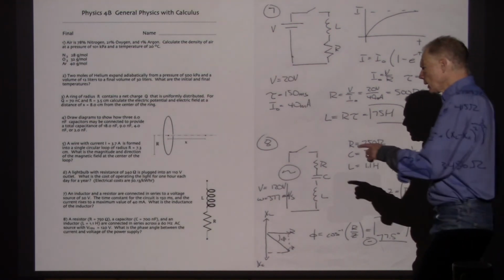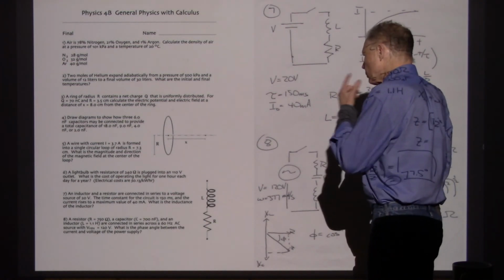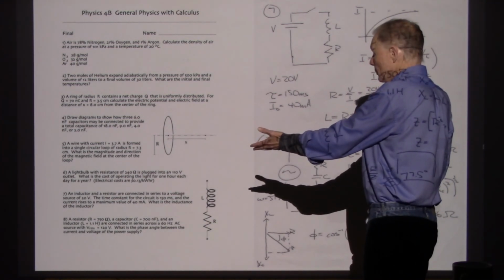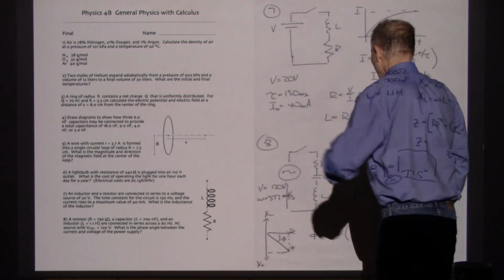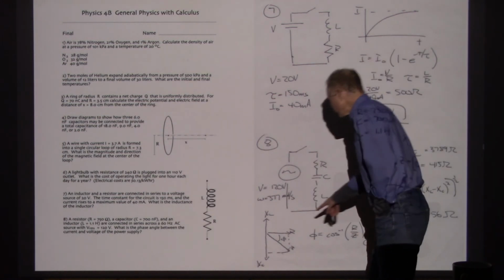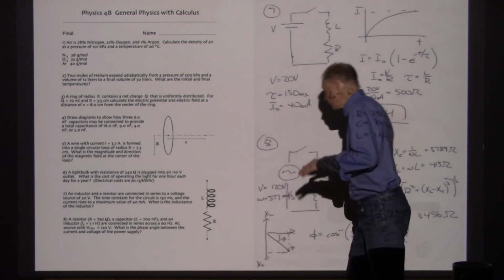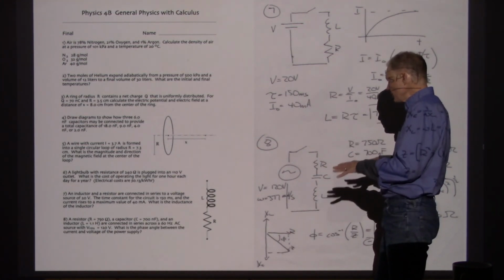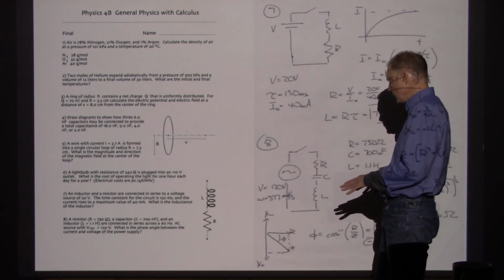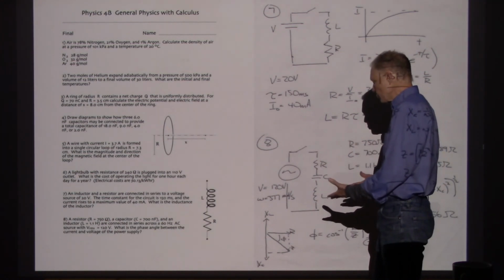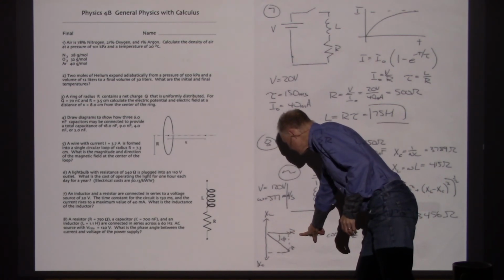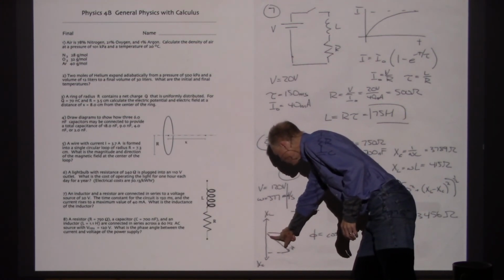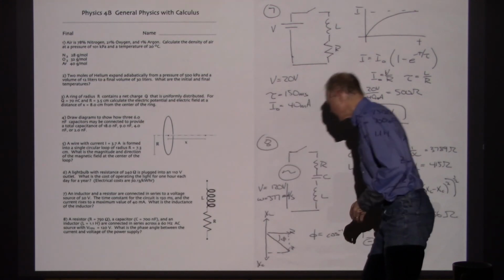So it is asking in the problem, I've got to go back and read the problem, what is the phase angle between the current and the voltage? So for the phase angle, using this impedance diagram as a phase diagram for measuring phases, the current is going to be in the direction of the resistance, and the total voltage will be in the direction of the total impedance.